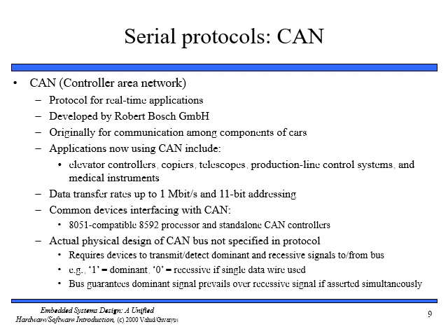So the CAN specification does not specify the actual layout and structure of the physical bus itself. Instead, it requires that a device connected to the CAN bus is able to transmit or detect on the physical bus one of two signals called dominant or recessive. For example, as I've already told you, a dominant signal may be represented by logic 0 and recessive by logic 1 on a single data wire.